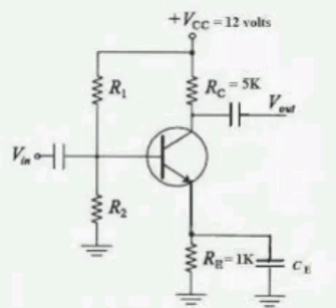Dielectric strength is defined as the maximum voltage required to produce a dielectric breakdown through the material and is expressed as volts per unit thickness. The higher the dielectric strength of a material, the better its quality as an insulator. Breakdown mechanism varies depending on the time of application of voltage and is classified as intrinsic or ionic breakdown, electromechanical breakdown, thermal breakdown, electrochemical breakdown, treeing and tracking, and internal discharges.